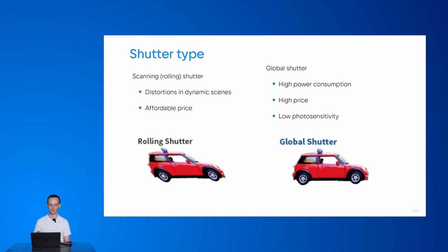Rolling shutter cameras could be installed in the laptop. So here I have a normal web camera, which is very tiny. So all the optics, all the sensor and everything, the whole board, it's all like this thing. This thin, it's very small, and I'm not sure that it's possible to create such a camera with the global shutter technology. And one more thing is the lower photosensitivity of these types of cameras. But still we use precisely them because they give us the ability to capture the scene that we are filming with very low exposure time, and all the straight lines continue to be straight after we have filmed them.